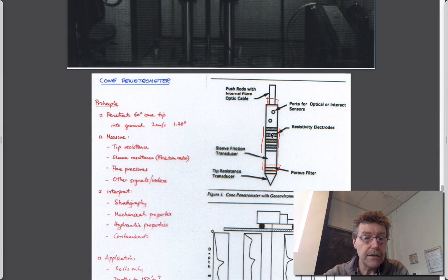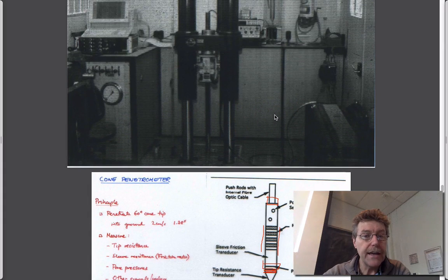So if you have a load here and a load here independently measured, this one will measure the tip resistance. The difference between this one and this one will be the amount of friction on this segment. So you can measure how frictionally it's resisted, a measure of sands, and what the end bearing of the clays might be, to be able to make some distinction. And it can measure the pore pressure, typically in a transducer, which is right on the shoulder of this probe. And so this is kind of the business end of this probe, which is on the end of this steel here that goes out of the bottom of a truck and into the ground.